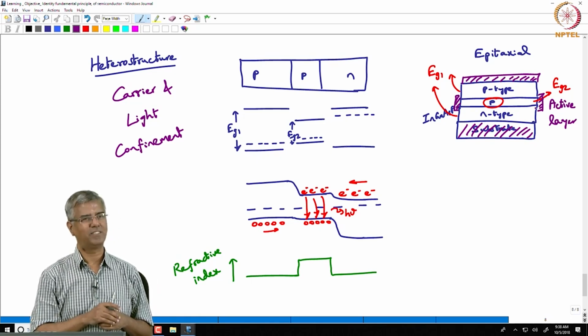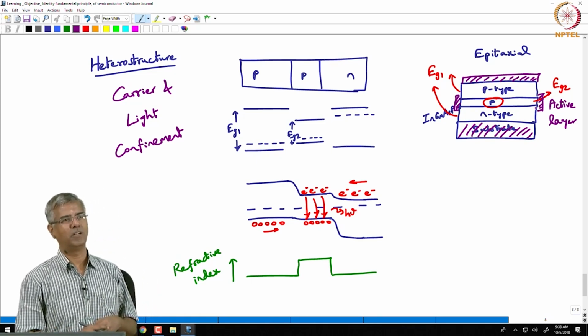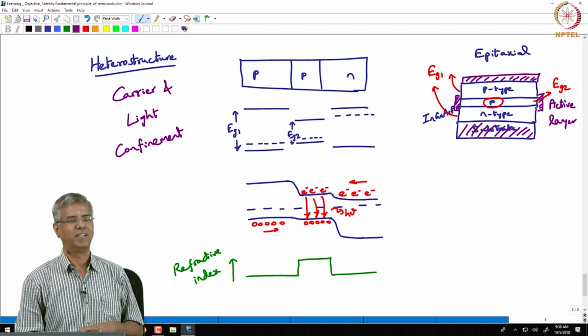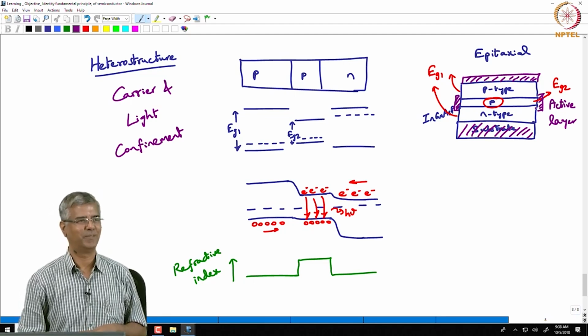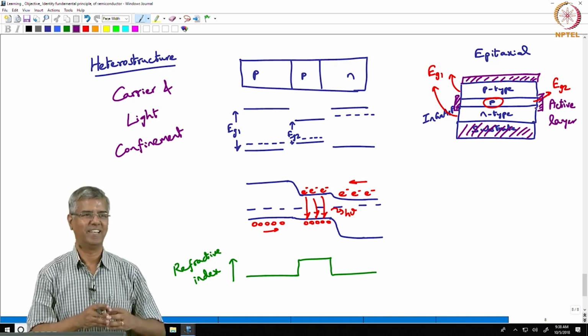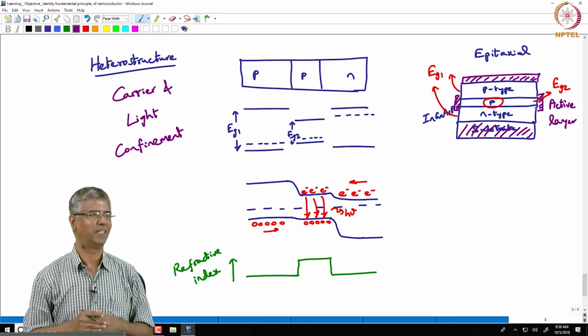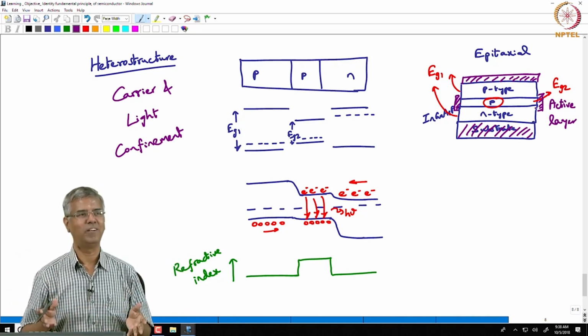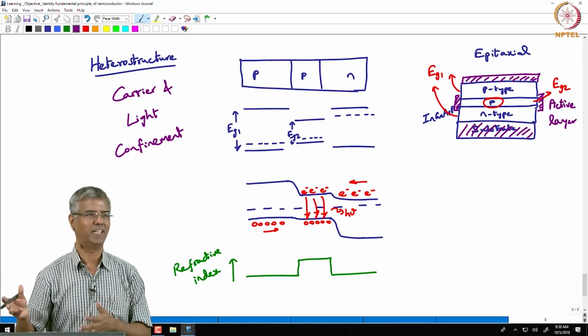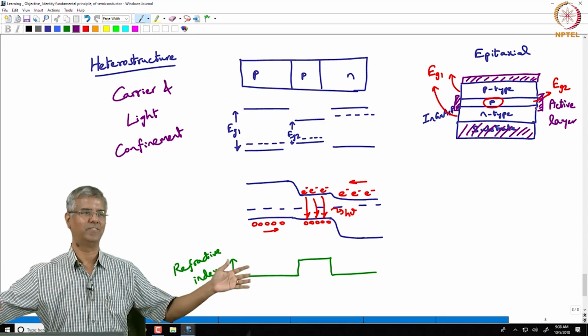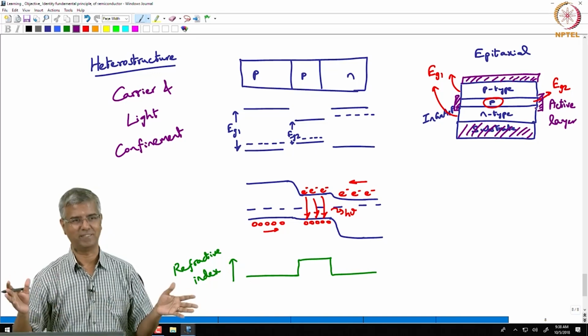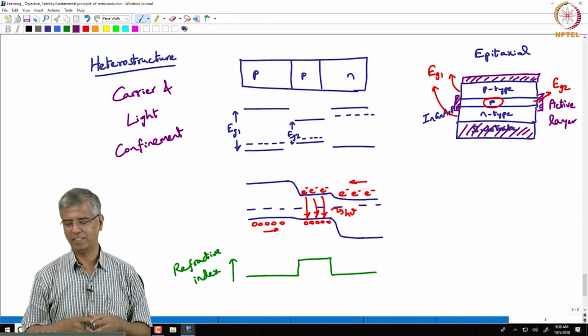Okay, that seems counterintuitive. You are talking about an optical surface and you want to make it rough, because rough essentially means that light will scatter everywhere from that surface. But that is absolutely okay, because most LED applications require light to be scattered over a wide region, the more the better, right.